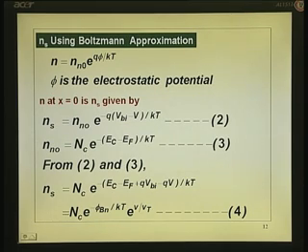So, what I do is I substitute this into that, and then Ns becomes equal to that quantity. Instead of Nn0, I put Nc e to the power of minus (Ec minus Ef), and this I put within that bracket, that becomes plus qVBI because minus is there, and this becomes minus minus plus.